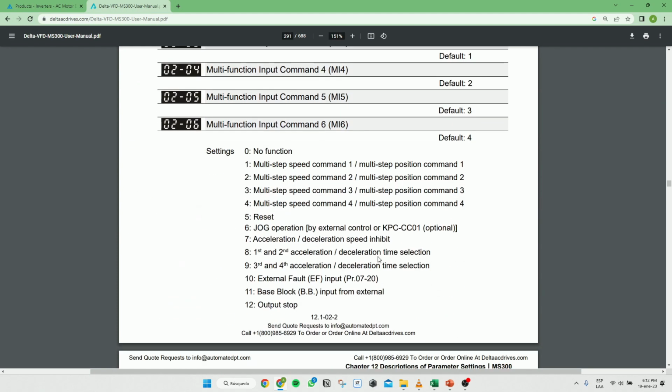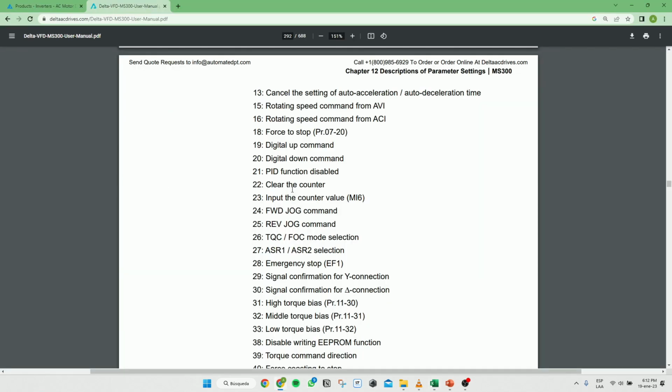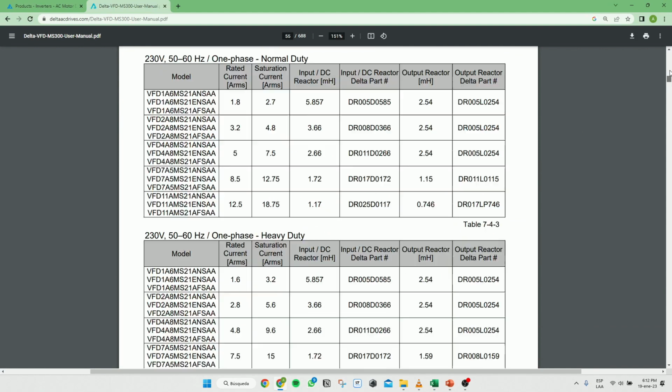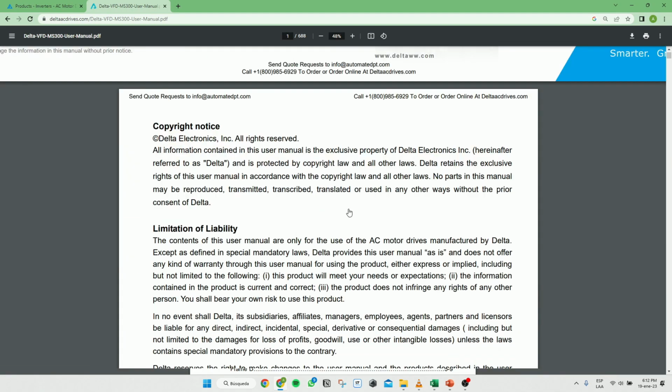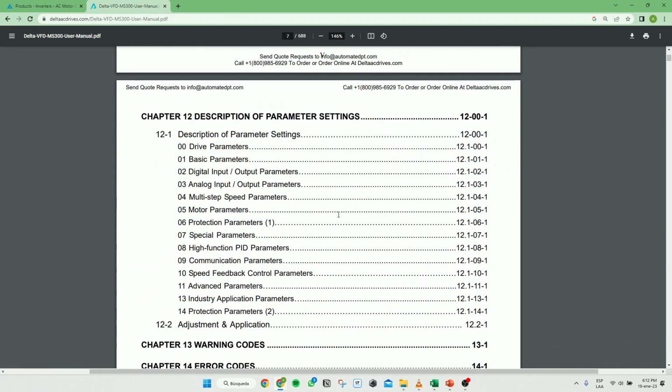Now, what else do we have here? So all we need here are the data plate information. So we have our voltage, we're missing our current. We can either find it in English or look here in our index, our options, okay? So here, description, protection parameters, and motor parameters. So we're close to 0.5. And it matches page 12.1. Okay, so this is 0.5.